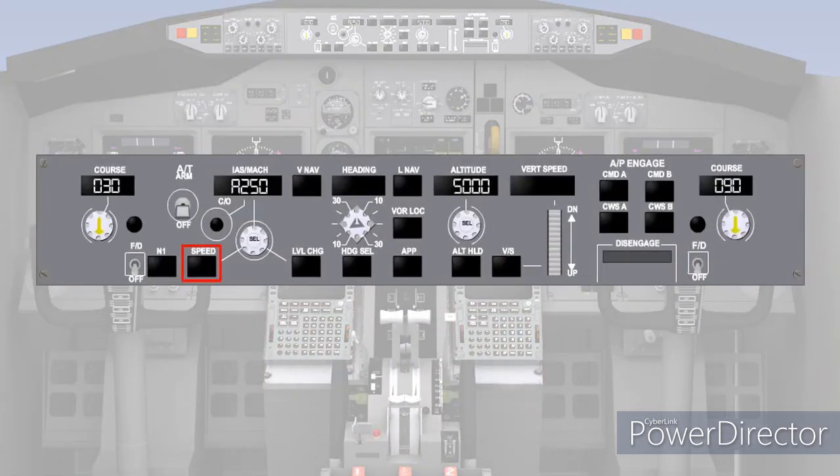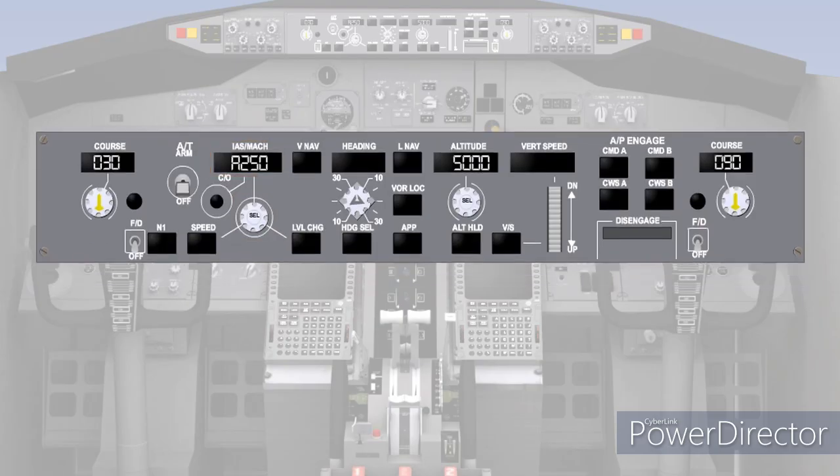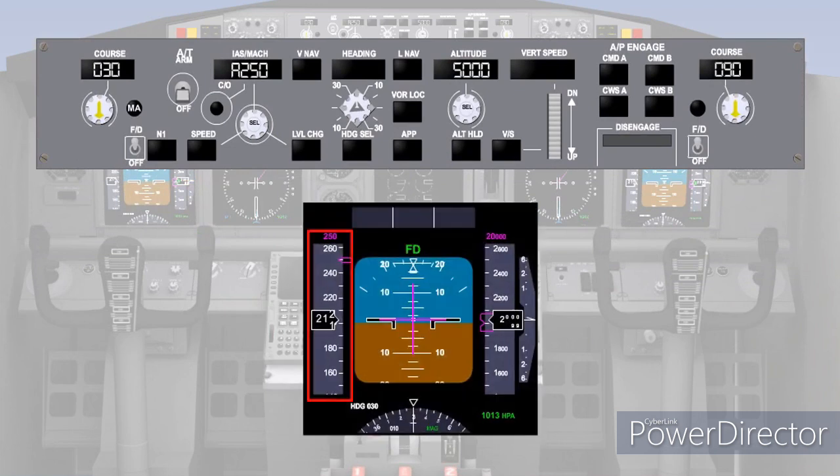We will give a brief overview of a typical autothrottle system to appreciate the compatible modes of autopilot and autothrottle. When engaged, the autothrottle can maintain either a target speed or thrust value. The speed target could be an indicated airspeed or Mach number selectable by the pilot using the speed selector on the mode control panel, indicated in the speed window, and on the primary flight display speed tape.